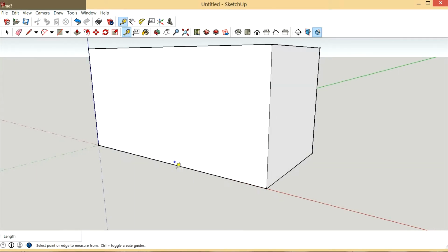The other cool tool that SketchUp has is a little ruler that you can dimension with or make these construction lines. You can see it's sort of a dash line. And so he said his deck was about 30 inches off the ground. So I'm going to come up 30 inches, and then I'm going to draw a line. I'm going to take my pencil tool here. One thing about SketchUp is that it's very intuitive. It's pretty cool. You see it snapping there to points, and you'll see some other cool things as we go along. So I'm just going to delete that